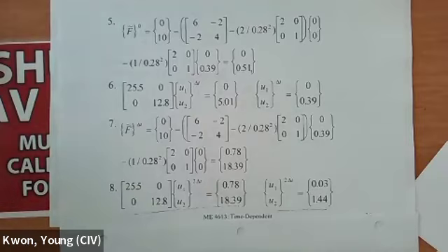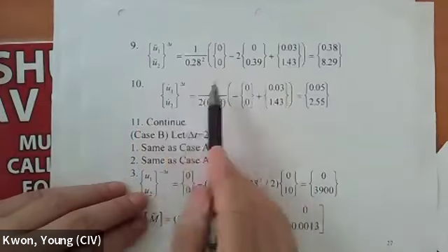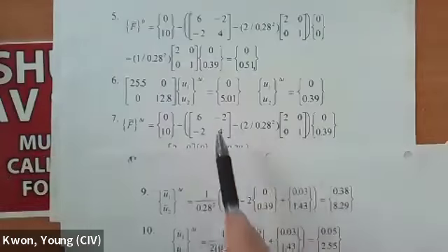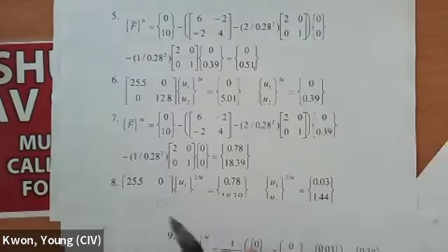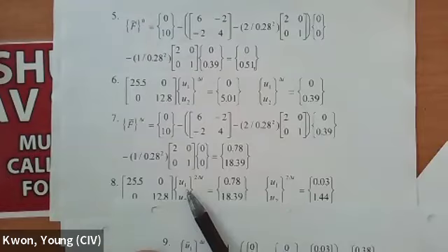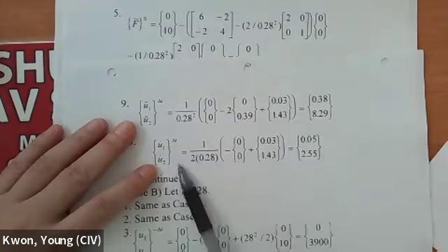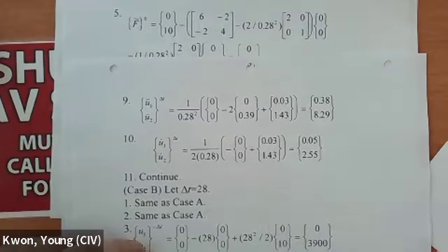And once you find displacement, then you can calculate acceleration and velocity from this central difference technique. So nothing new in here. However, with this technique, if you are not interested in velocity and acceleration, you don't have to calculate that. You just simply calculate displacement all the way from 0 to the final time. But in most cases, you are interested in velocity and acceleration, so you need to calculate that also every delta t. So that's what we are going to do in a computer program over and over.